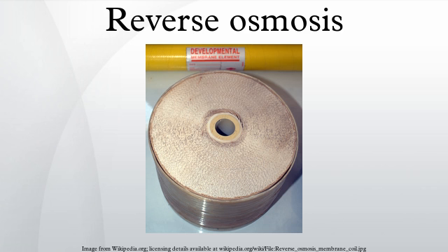High-pressure pump. The high-pressure pump supplies the pressure needed to push water through the membrane, even as the membrane rejects the passage of salt through it. Typical pressures for brackish water range from 225 to 375 psi. In the case of seawater, they range from 800 to 1180 psi. This requires a large amount of energy. Where energy recovery is used, all or part of the high-pressure pump's work is done by the energy recovery device, reducing the system energy input.